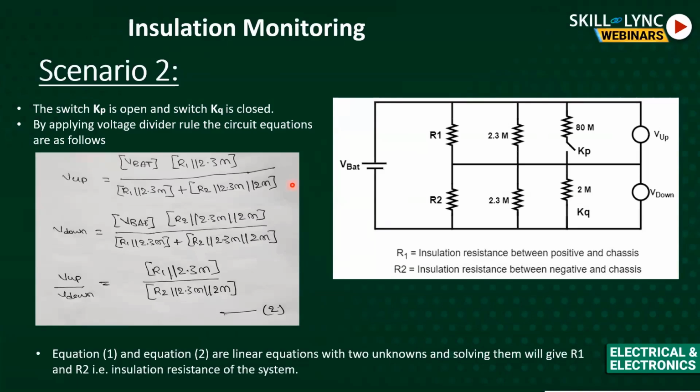First thing is we are using an electric powertrain. For a passenger vehicle, we require higher voltages to operate efficiently and, at the same time, to reduce the cost of the automobile. So if you're going to higher voltages, you have certain hazards, like somebody getting a shock. That is one thing which will be prevented by this insulation monitoring. That means if the insulation breaks or is reduced, I won't even connect the battery.